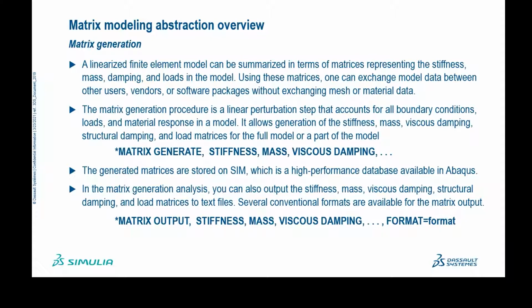So the matrix generation procedure is a linear perturbation step that accounts for all the boundary conditions, loads, and material response in the model. And this capability allows the generation of the stiffness, the mass, the damping, and the viscous damping or the structural damping, and the load matrices for the full model or part of the model depending on the need.